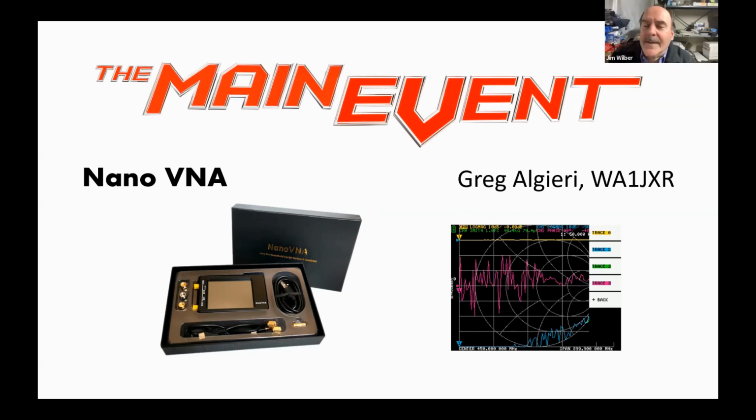Another question. I understand the purpose and value of the port saver that you recommended here. If you were also interested in saving yourself a lot of twisting of SMA connectors on and off, you could use an SMA to BNC type connector here. Is the insertion loss likely to be about the same there? Have you been down this road already?